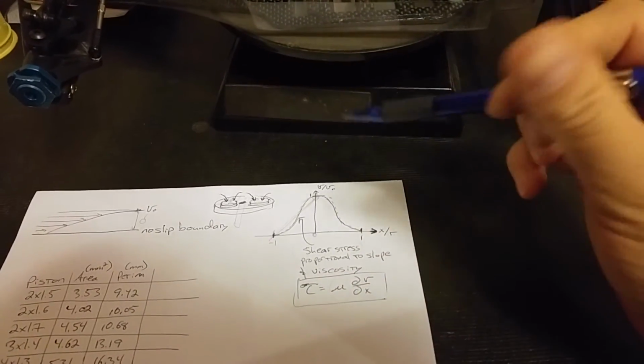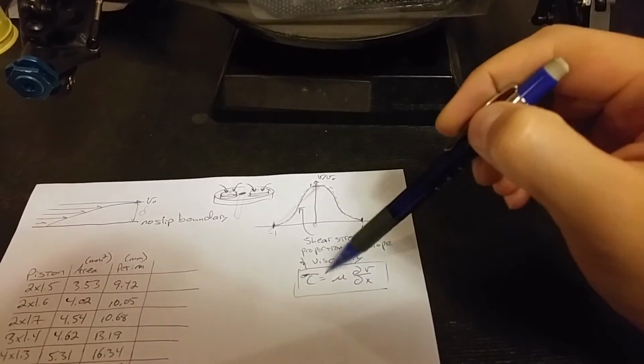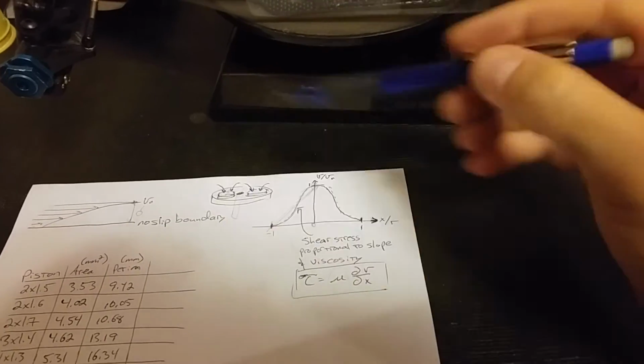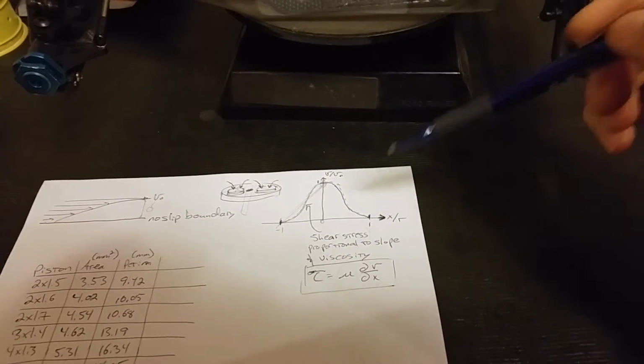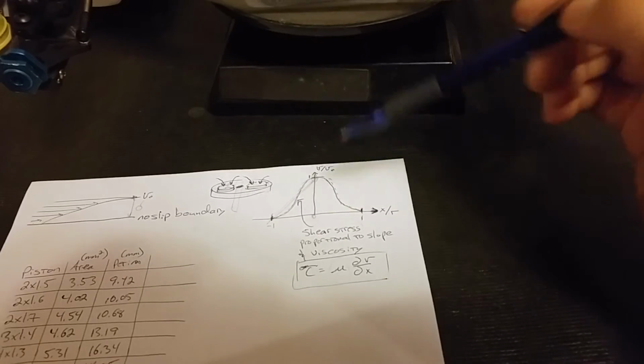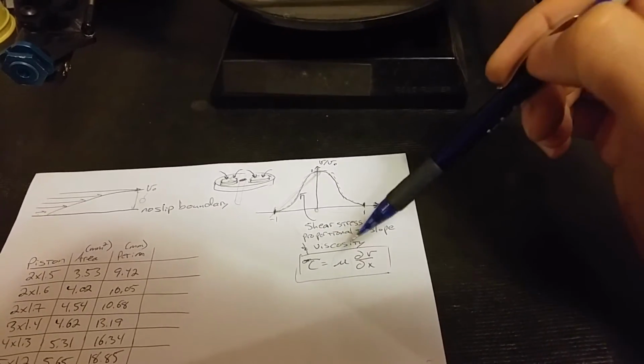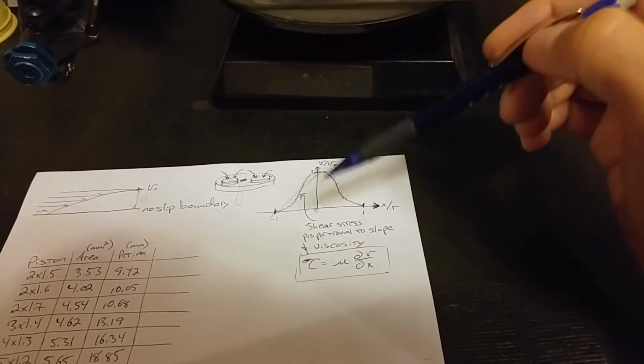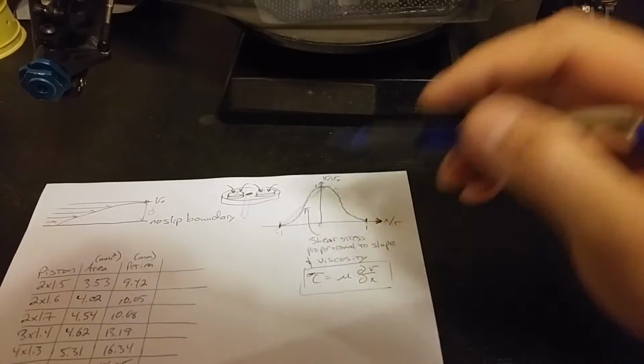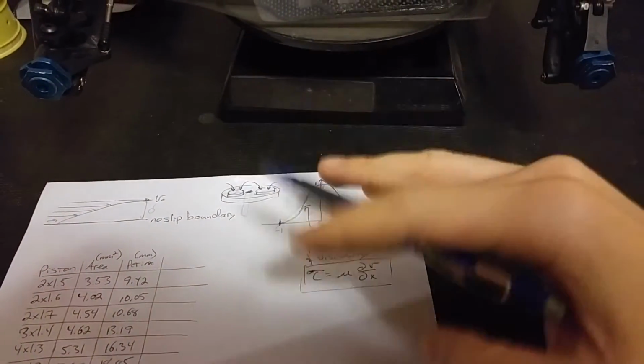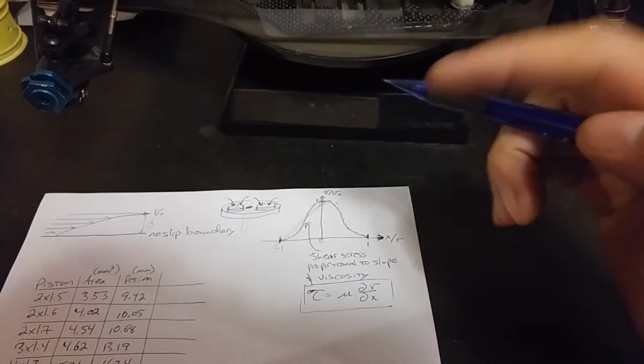So if you have a higher viscosity shock oil, if you go from 25 weight to 35 weight to 45 weight, for example, all else being the same, you will end up with a higher amount of pack in the shock, which basically means that your high-speed damping is higher.